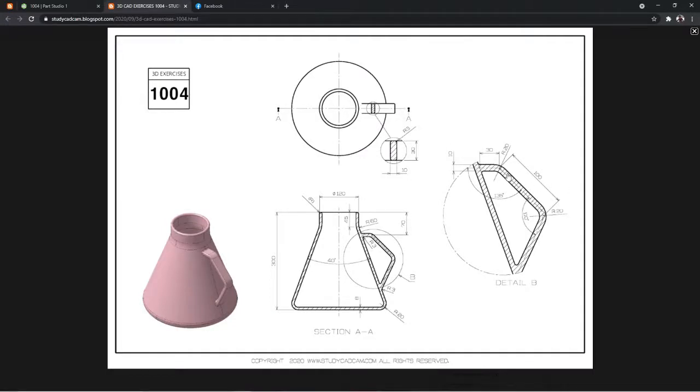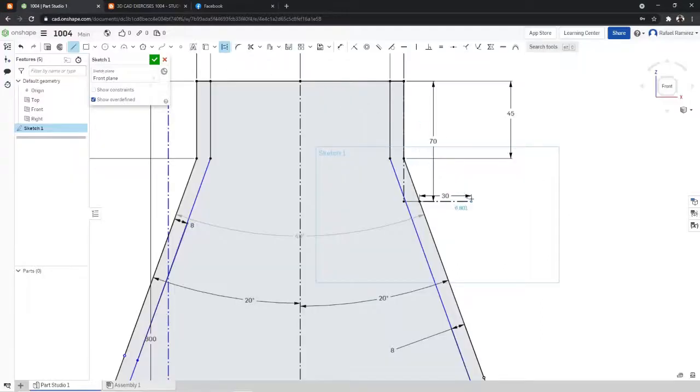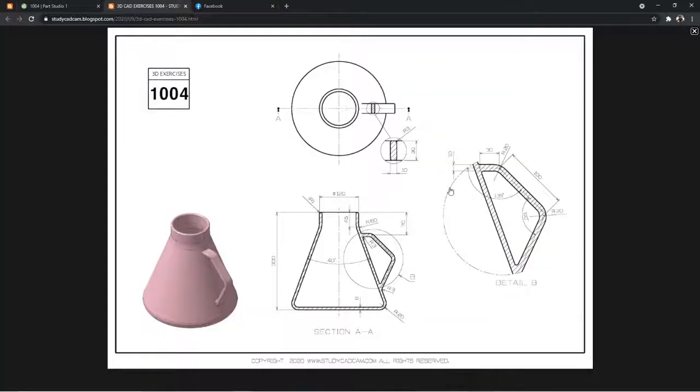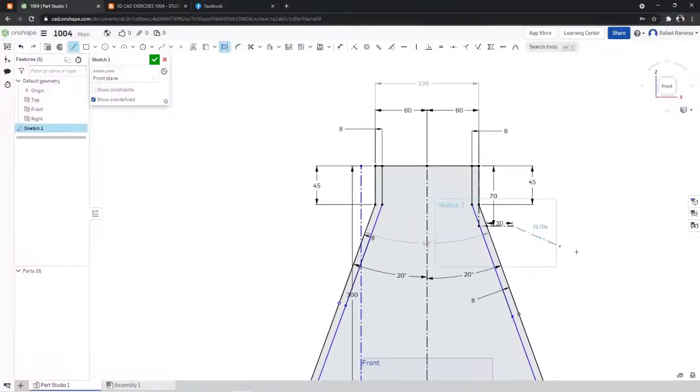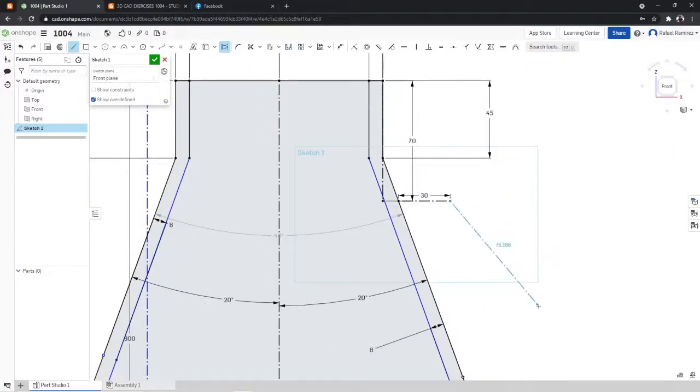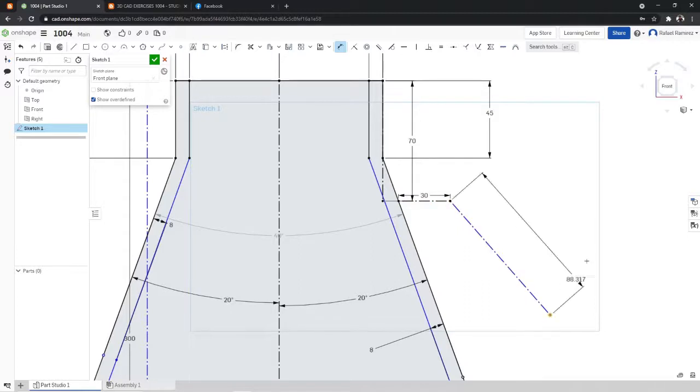And then what you're going to do is draw a line down to the right at exactly 135 degrees from the horizontal, and the length would be 100 millimeters. So we're just gonna click anywhere. It's okay if you were not able to indicate the angle first, as long as you specify that this one is 100 millimeters.